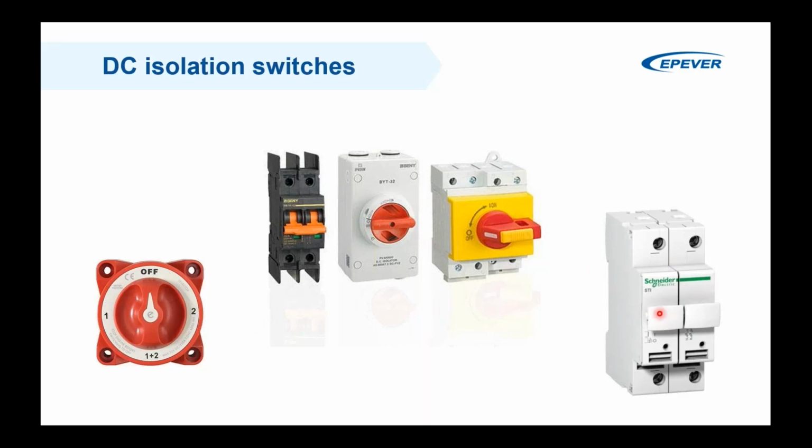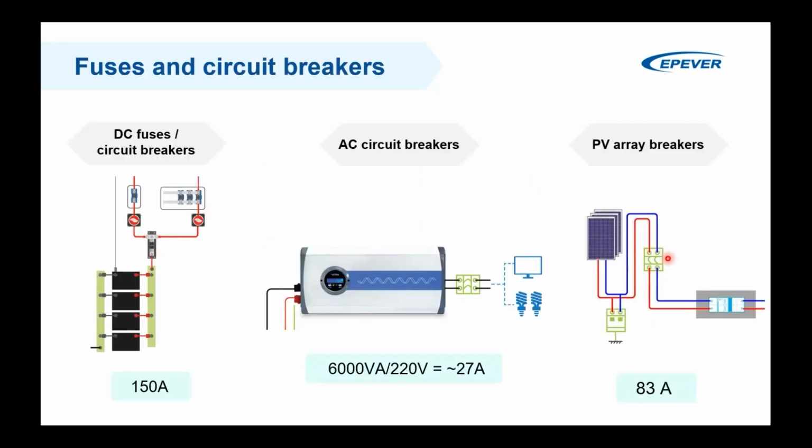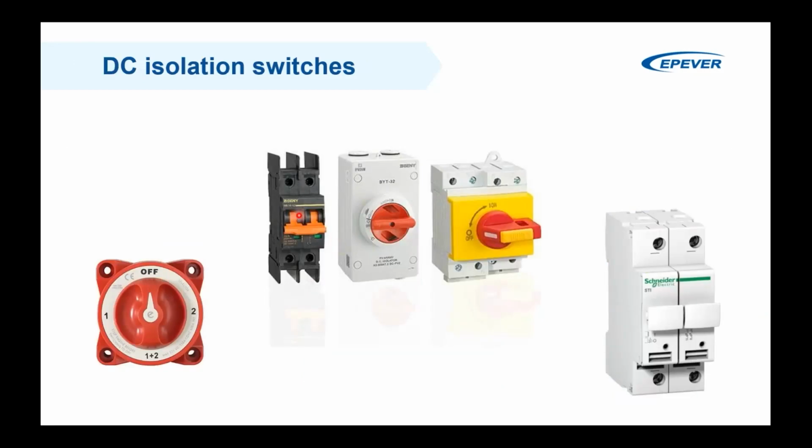This is also an example of a rail-mounted or DIN-mounted circuit breaker for land-based battery PV systems. Normally, when the voltage is high, you use these sorts of fuse holders and breakers. And these are also the isolators for PV panels, for example. This also makes it easy. So we have isolation here. You can use either of these types of switches in your system just to make sure that you have safely disconnected the solar panel from your system.